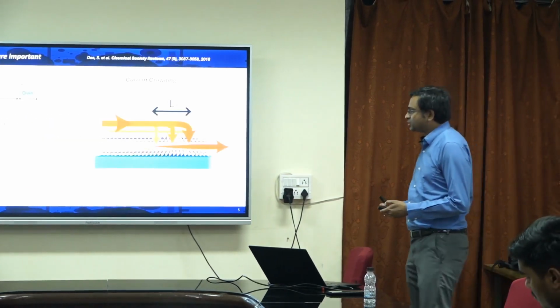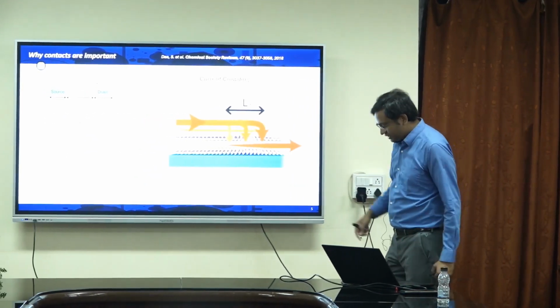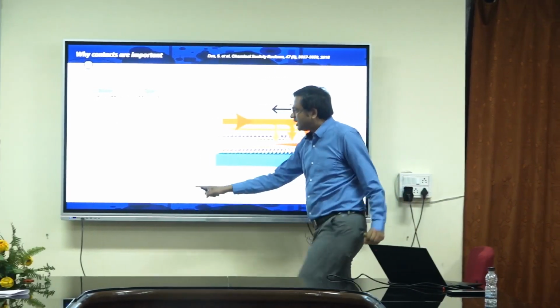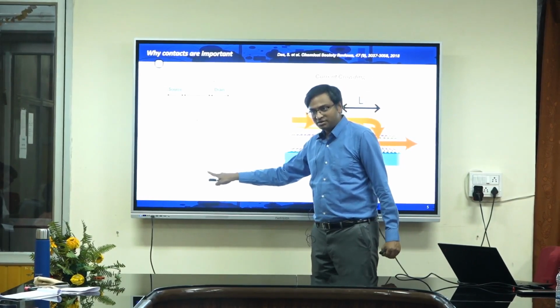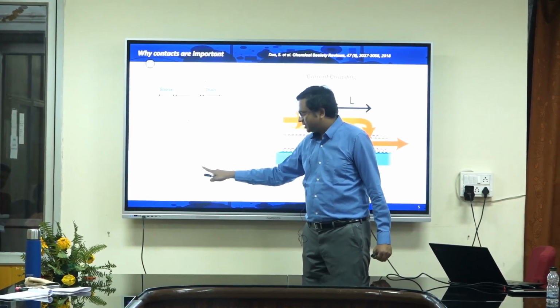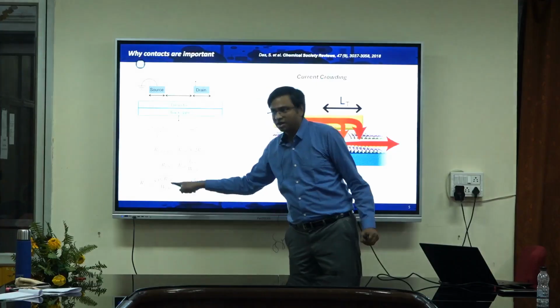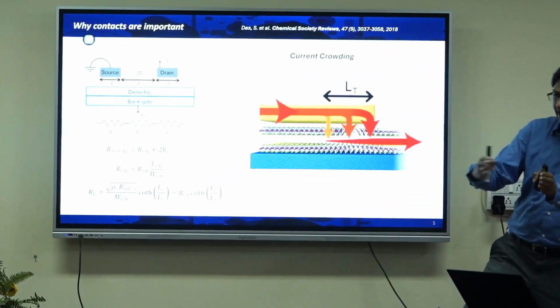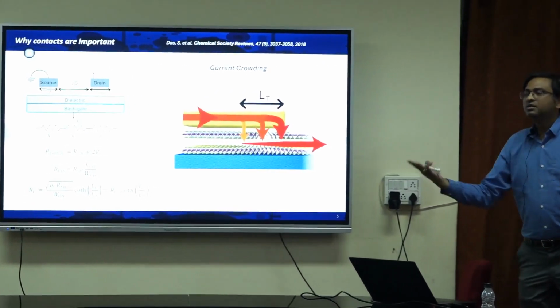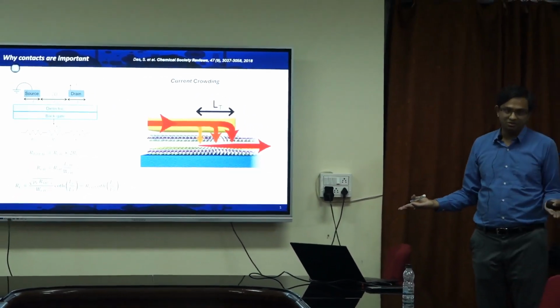If you go back to this equation, you see that both RCH and RC become smaller with the width of the channel, which means that if I make my channel wider and wider, my resistance will anyway go down.